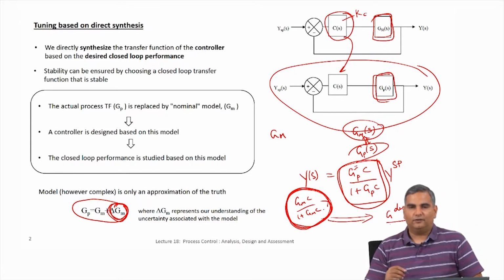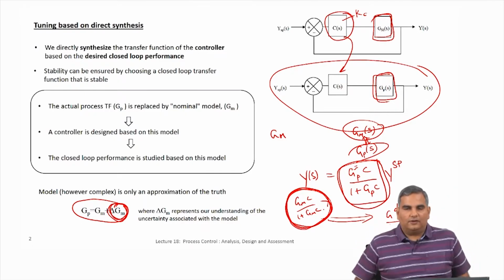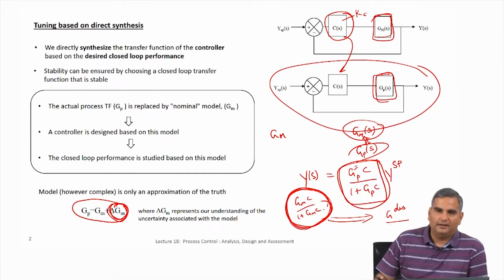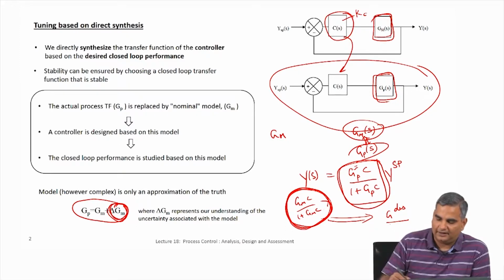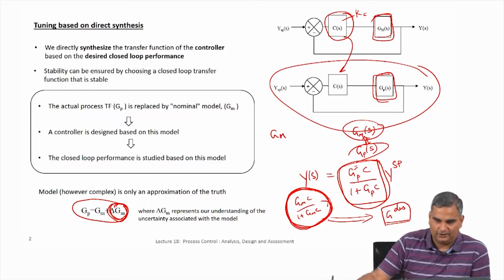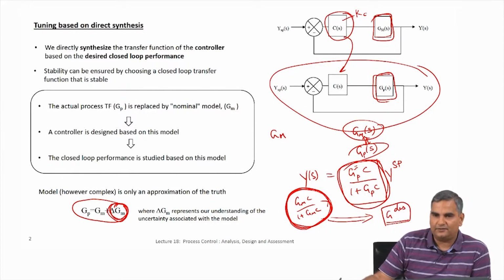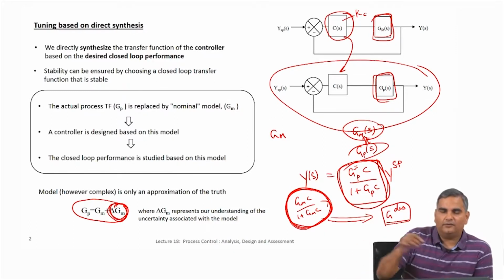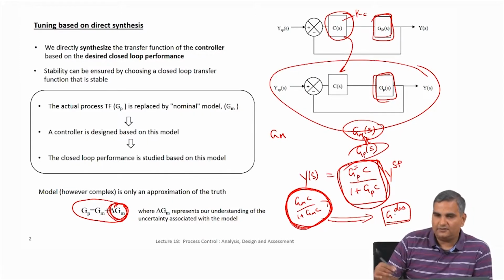Okay. So, instead of doing this roundabout way, it seems, where I am going to choose a controller, find the limits of stability and then come back and back off and then say okay, that is heuristic and I can see how well that does by putting into this, is one way. Instead of that, you might say, look, I am going to look at something as my desired transfer function, and since this is the ultimate closed loop, when this equals this desired transfer function, then I have got everything I want. I do not have to really worry about stability here, in the sense that I can choose a G desired which is stable, right.